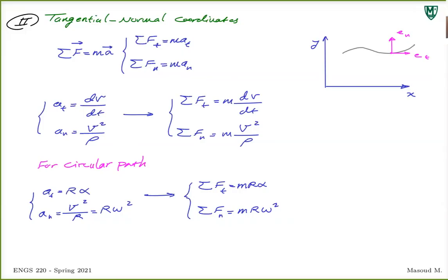The left side is whatever we get from the free body diagram. The right side is whatever we get from the kinetic diagram. Remember, we said the kinetic diagram, or a diagram that shows the inertial forces, is basically the same. We draw the object and we put the components of acceleration, in this case tangent and normal components, and just multiply that by the mass. That gives us the values for the right side of this set of equations. That's pretty much all there is to it.